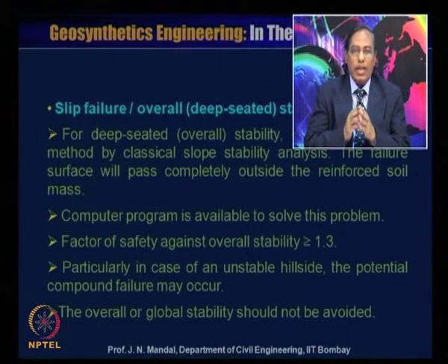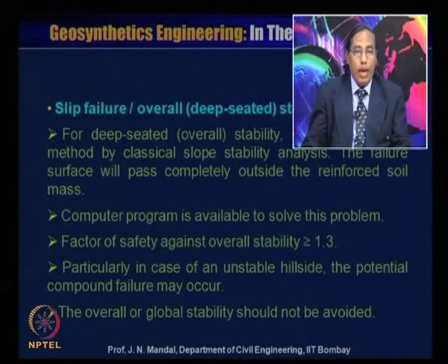You check the factor of safety against overall stability, and it should be greater than or equal to 1.3. Particularly in the case of an unstable hillside, a potential compound failure may occur, so the overall or global stability should not be avoided.